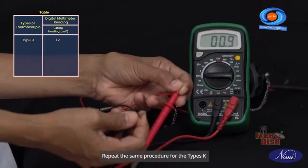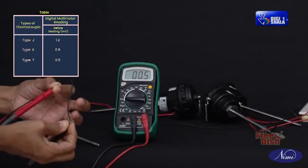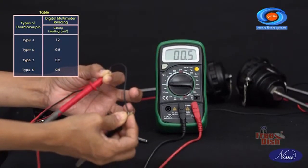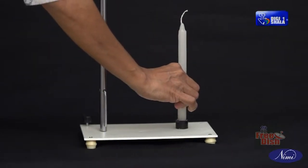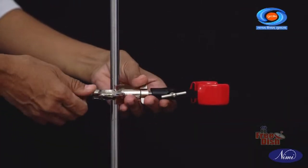Repeat the same procedure for the type K, type T, and type N thermocouples. Record the values in the table. Place the candle on the stand. Fix the thermocouple sensor to the stand.